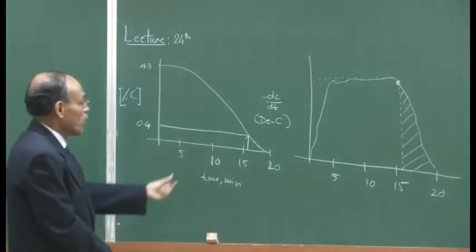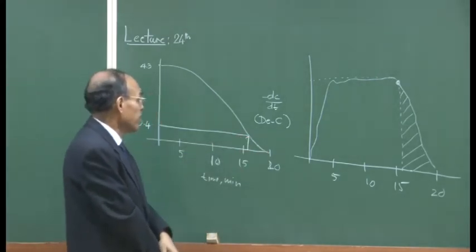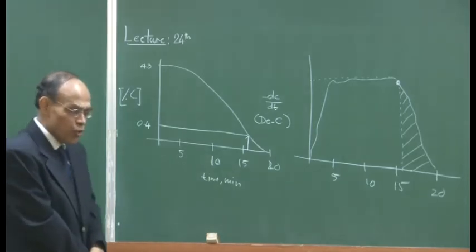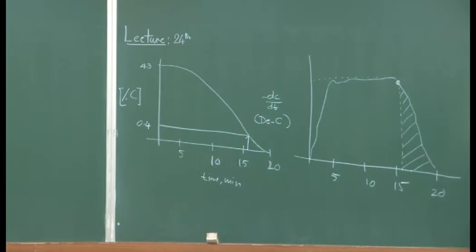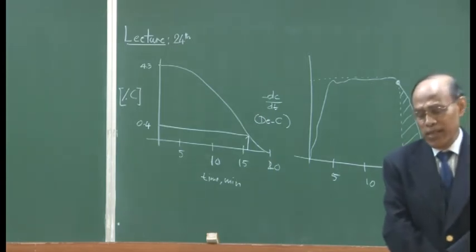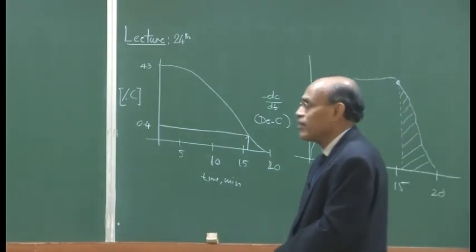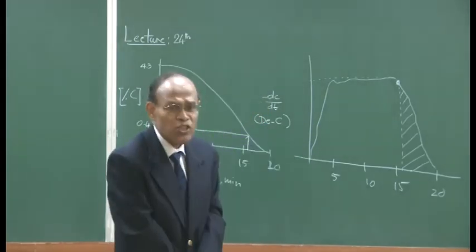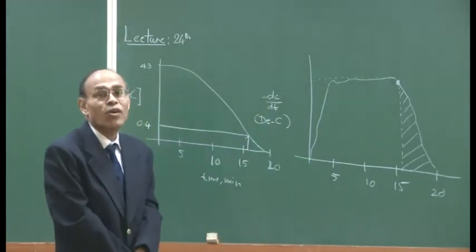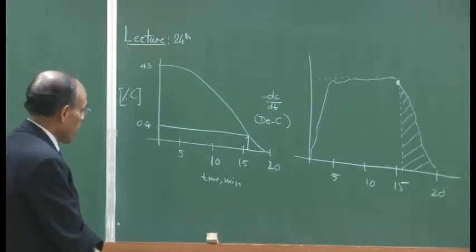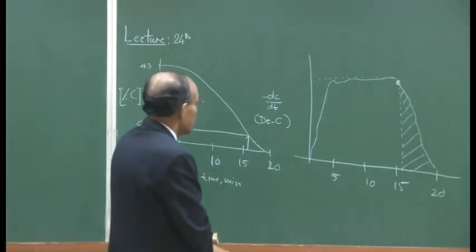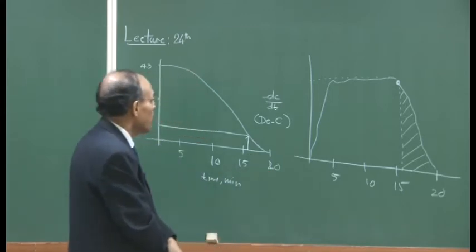So, therefore, it is very important for us to know the nature of this tailing graph, and I have told you that decarburization basically is a phenomenon whereby melt phase transport of carbon has typically been shown to be rate limiting. So, it is not the chemical reaction, the carbon oxygen reaction or the carbon FeO reaction, dissolved carbon or slag FeO reactions. It is basically the transport of carbon within the melt phase.